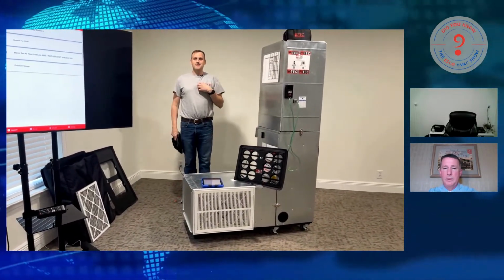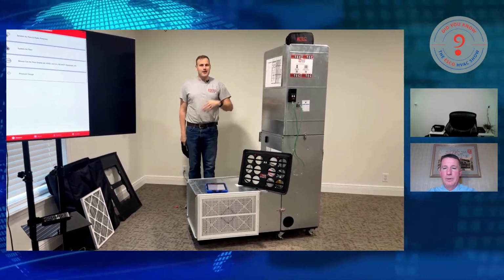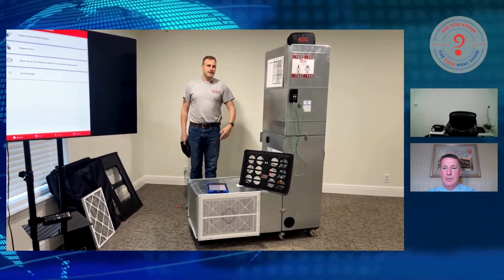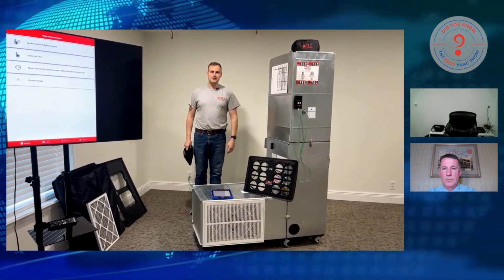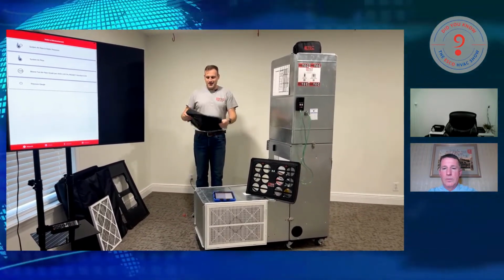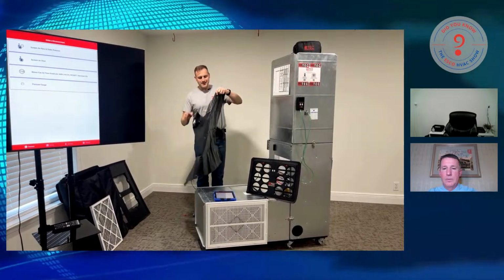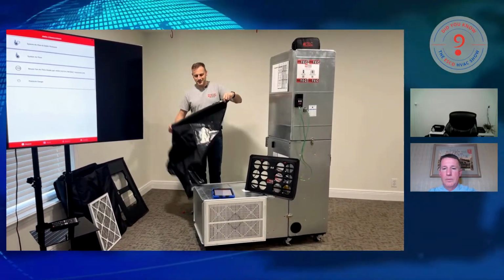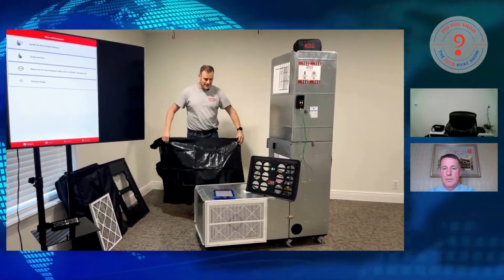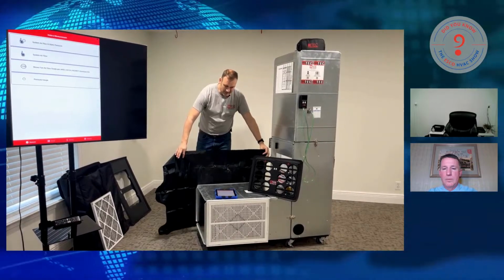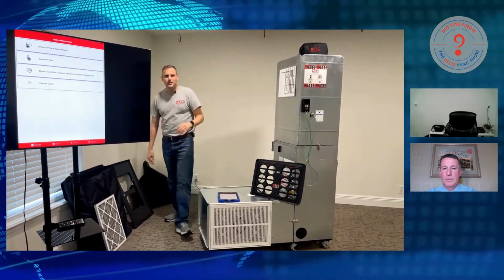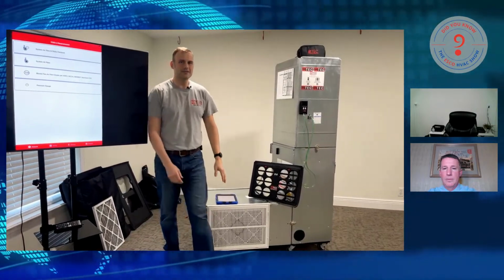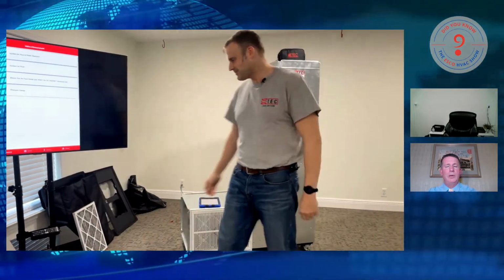One little tip that I've come to learn with my kit, I've run it with friends in the field. Every now and then I'll go jump in the truck with a guy to go deploy the tool, keep my feet wet, right? So I took a large contractor garbage bag when I have a double multiple return, and when the fan's running, I'll lay it up against the return at the ceiling and let it suck it tight. That has worked well for me for a quick way to blank off the additional return, but we're going to get to that.